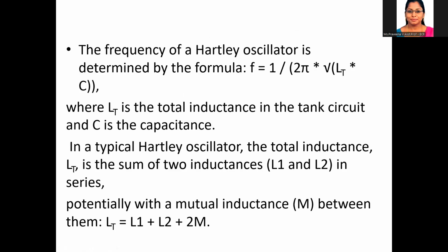And for mutual inductance, LT equal to L1 plus L2 plus 2M, where 2M is the mutual inductance and L1, L2 are the two inductors connected in series. You have to remember this.